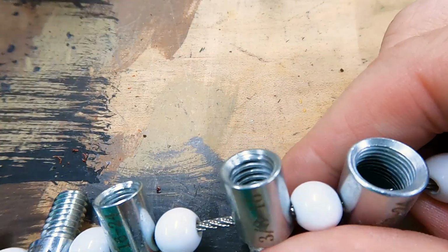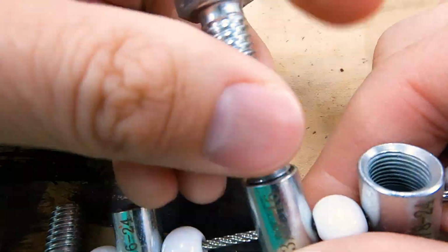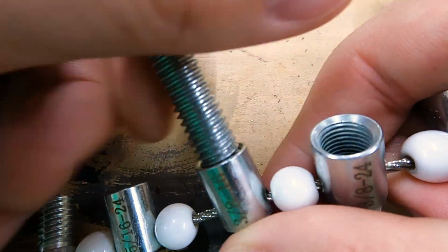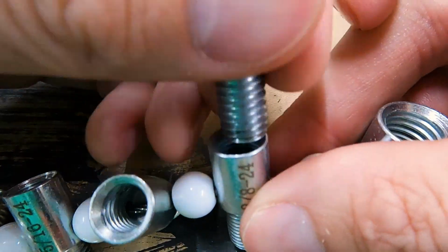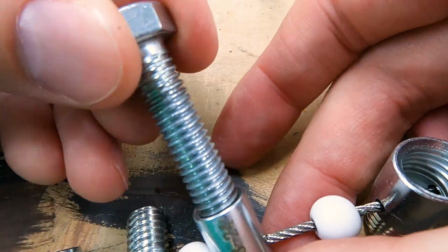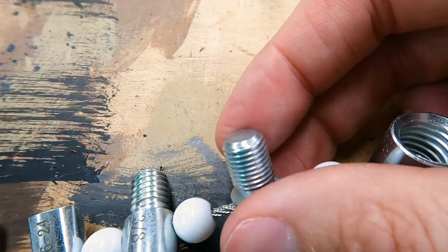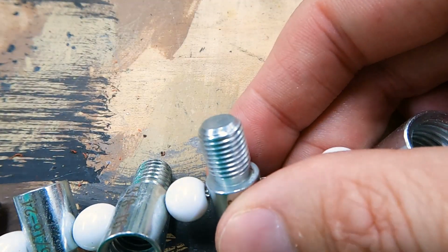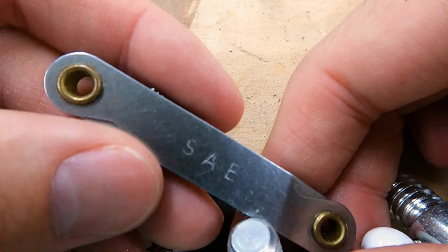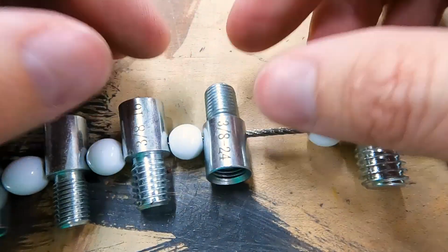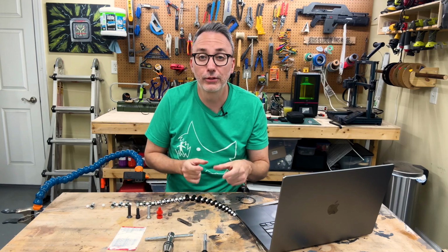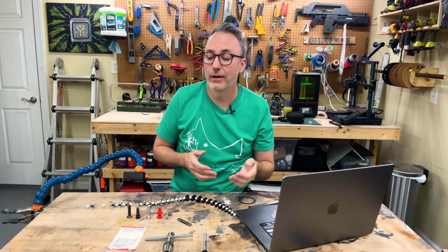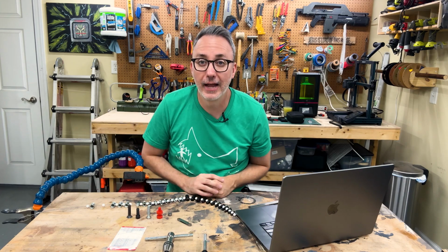And we can flip it over and check it in the internal or the external. And sure enough, that screws on. If I were to go over to the 3/8-24 and try to screw it in, it gets stuck. So it's not 3/8-24. So if you know its nominal diameter is 3/8, but you don't know if it's 24 or 16, and you don't have one of these to check it, then you can use one of these. Before I had this, I would take bolts to Home Depot, and they have these mounted on the wall, and you can check them there. I got tired of doing that, and I was like, I just want one for my house. So I ordered this off Amazon, and it's been really handy.